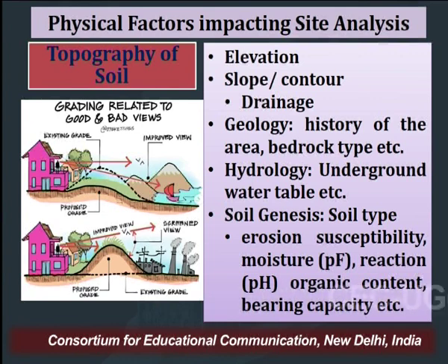And drainage of water is one of the important aspects that has to be taken care of while designing. So, while doing site analysis, the elevation, the slope, the contour and the way water moves out from the site is very important.